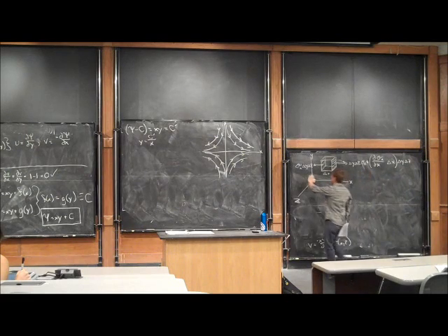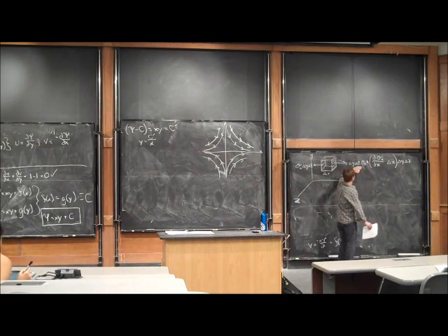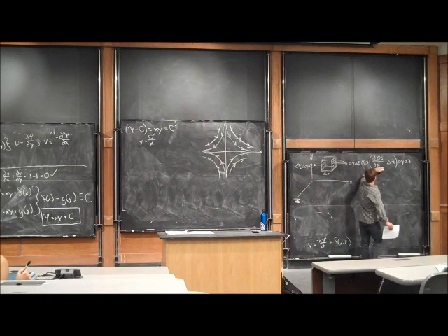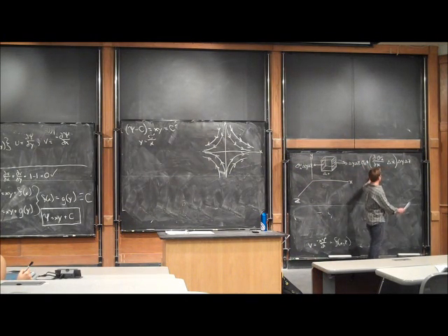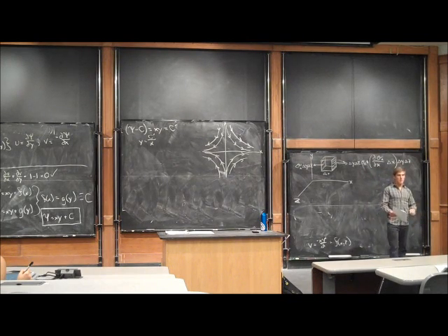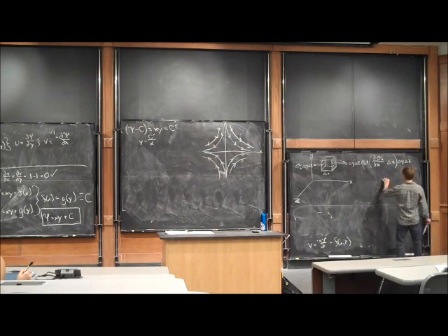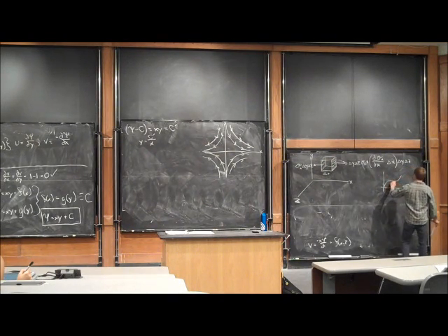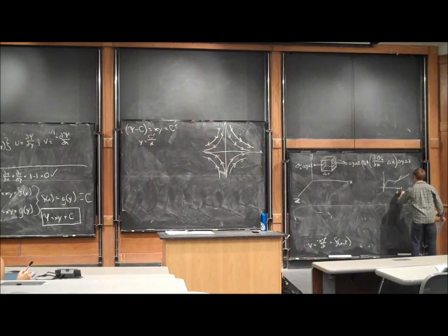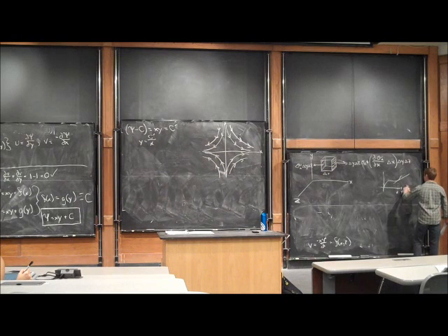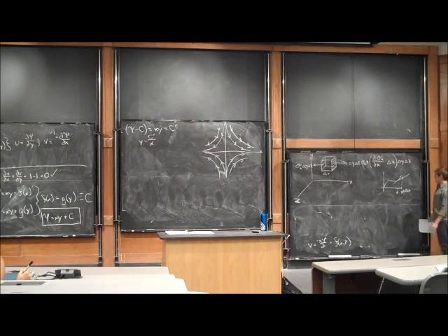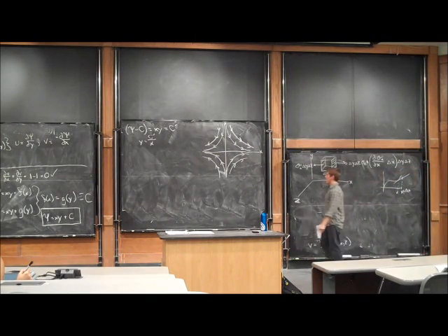So the force on this side of the cube is equal to the force on this side of the cube plus how that force changes with respect to the x direction times the translation in x. So that's just saying, if we're looking at a function, if we look at the derivative at this location x, the value at some x plus delta x can be approximated as the derivative times that translation. So it's the same sort of argument that we've seen in math in the past.